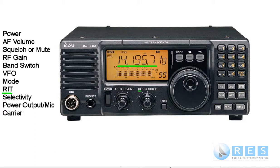Here's the RIT. It's the outer knob. This is the RIT here, this knob. The receiver incremental tune, or RIT, enables you to change your receive frequency without changing your transmit frequency. So if the operator that's transmitting to you is slightly off frequency, you can use your RIT to get him nice and clear without changing your transmit frequency. That being the case, when you transmit back to him, he won't have to make any adjustments to his receiver. That's the receiver incremental tune, or RIT.